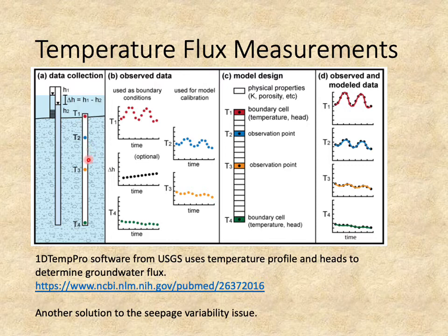And you measure several temperatures with depth. We have variation at the surface shown here, and then we have the advection dispersion equation. In this case, we'd have water flowing downward into the lake bed, and that would be carrying this signal of heat downward. It would be advecting; we'd have heat transport downward. If we had the opposite case, with water moving upward, we'd have only back diffusion of the heat and less advection, and no advection downward.